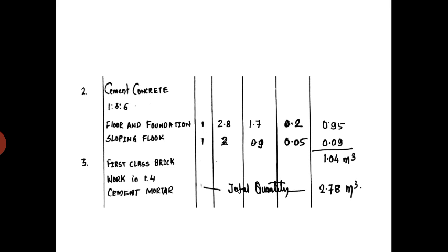Cement concrete, that is 1:3:6 for the floor foundation and the sloping of the floors. That also we have calculated, that is 1.04 meter cube.